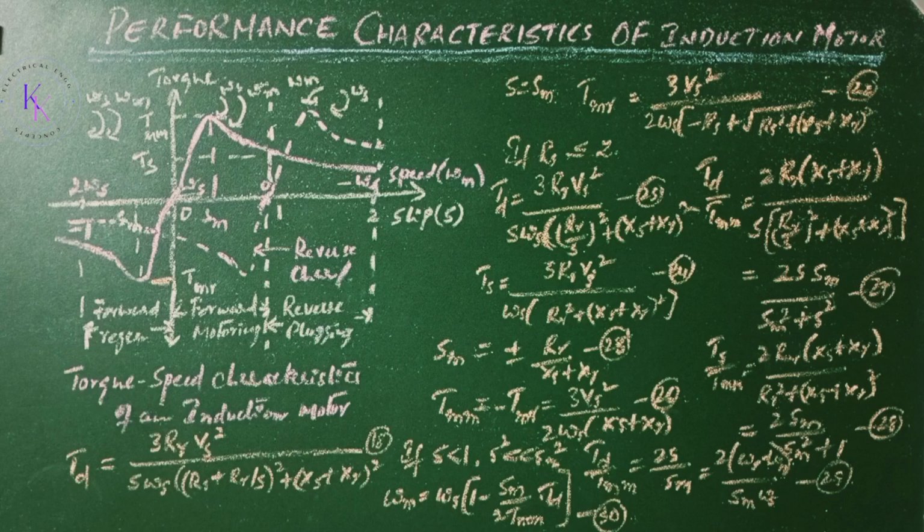The speed torque of an induction motor can be varied by one of the following methods. First one, stator voltage control. Second one, rotor voltage control. Third one, frequency control. Fourth, stator voltage and frequency control. Fifth one, stator current control. Sixth one, voltage, current and frequency control. To meet the torque speed duty cycle of the drive, the voltage, current and frequency controls are normally used. We will see the different methods of controlling in the next video.